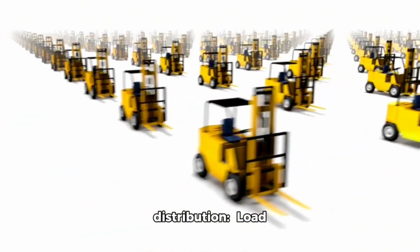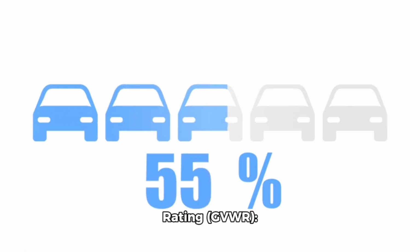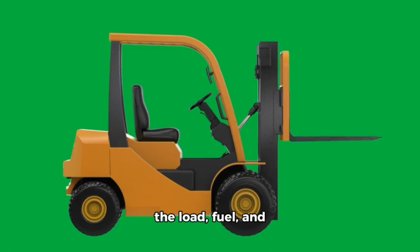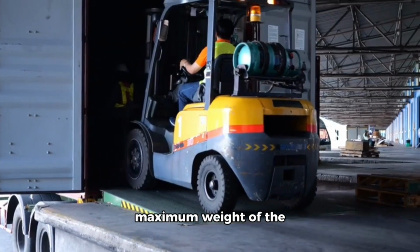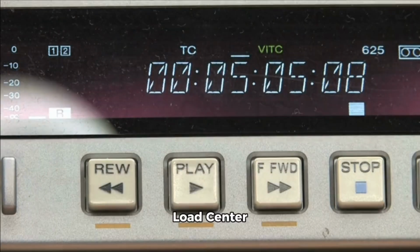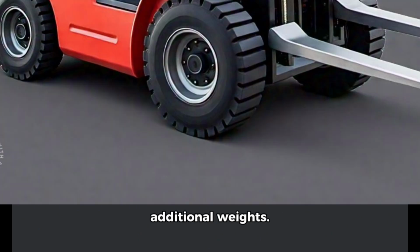Load calculation principles. 1. Gross vehicle weight rating, GVWR. The maximum weight of the forklift, including the load, fuel, and attachments. 2. Load capacity. The maximum weight of the load that the forklift can handle. 3. Load center distance, LCD. The distance from the front of the forks to the center of gravity of the load. 4. Weight distribution. The distribution of weight on the forks, including the load, attachments, and any additional weights.